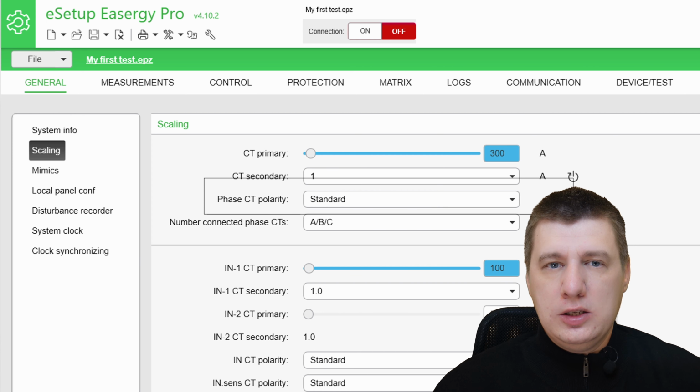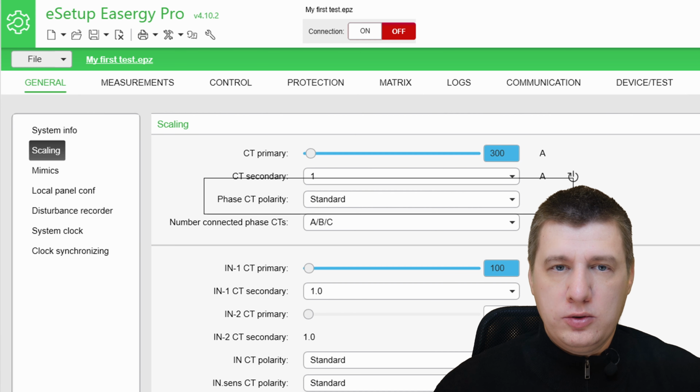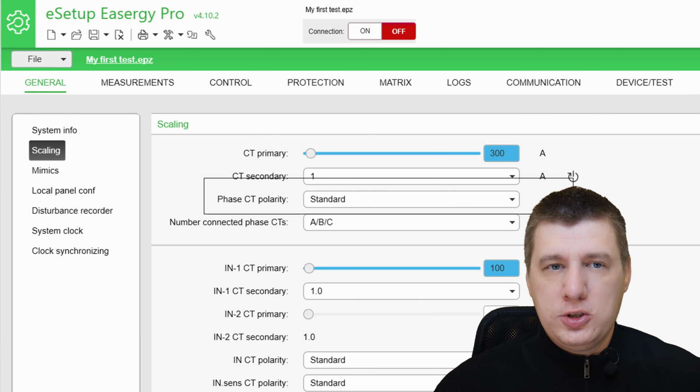Incorrect polarity can lead to two primary types of failures. Example 1. Directional protection failure. A directional protection stage determines if the fault is forward or reverse. If the CT polarity is reversed, the relay will see a forward fault as being in the reverse direction, and the directional phase overcurrent function will not trip for a fault on the line it's supposed to protect, but it might trip unnecessarily for a fault elsewhere in the system.